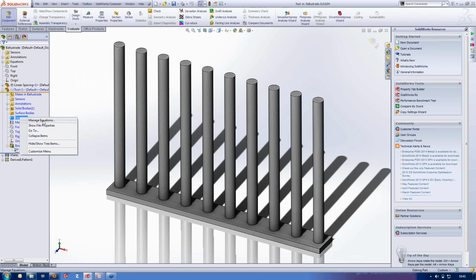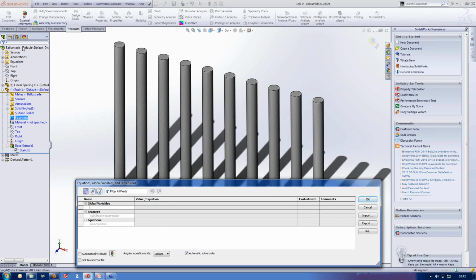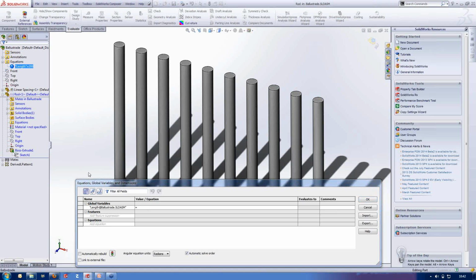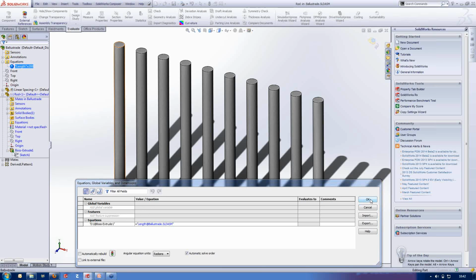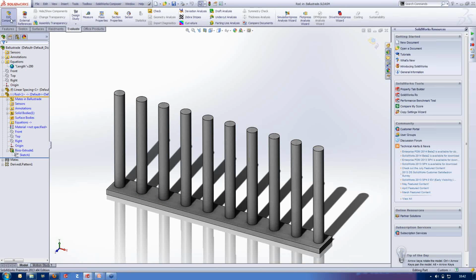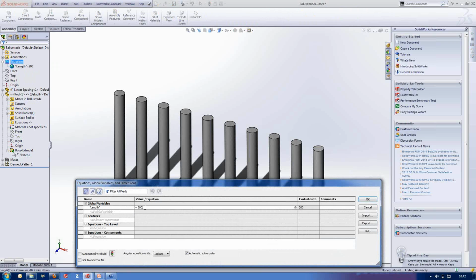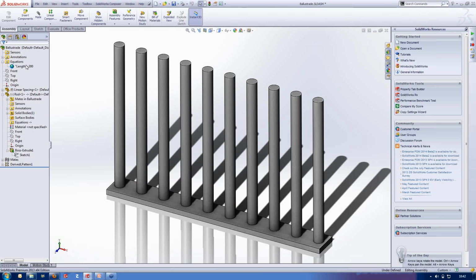let me get my brain in order. So you can see here I've picked up length at balustrade. If I'd done that on the other side, which is what I meant to click if I'm honest, we can pick this item and say we want that dimension, and we can say it equals length at balustrade. Does that explain how to get there? It doesn't necessarily appear in the various equations dialog, but we've got that length at balustrade which we can reference. And then these get shorter. So as I edit this global variable, if I make that 300 again and hit OK, my rods get longer because they're being driven by the value at the top level. Hope that explains that one. Right.